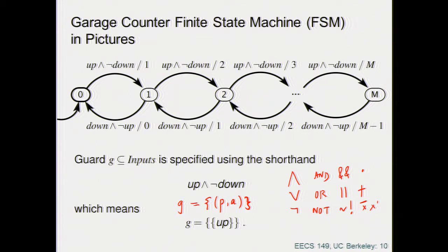Very nice, very good. So it's called a self loop, right? So you don't move, right? So big information. But if you don't say it, it means that the finite state machine is incomplete, meaning that I don't give you the transitions for all possible combinations of the inputs. In this particular case, it's incomplete, but it's obvious how to make it complete, which means for all possible combinations of inputs and outputs, I always have a transition that tells me what happens, right? It's just I chose not to put it down because it's trivial, okay?